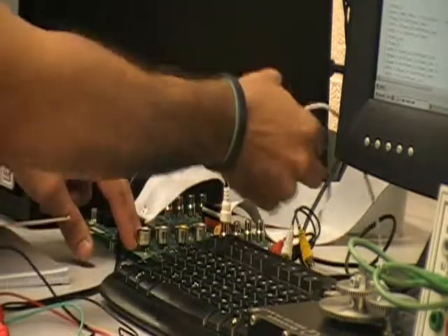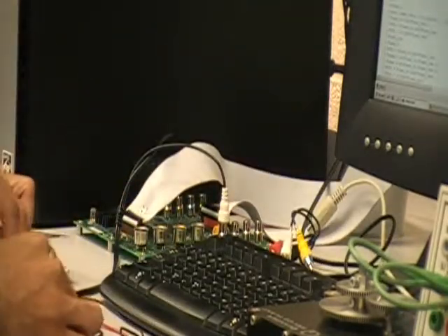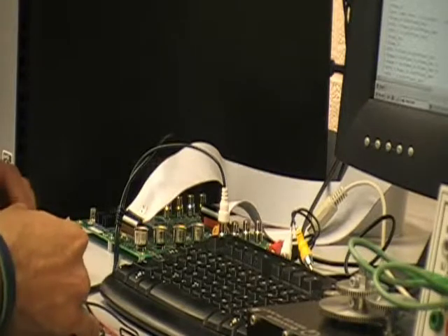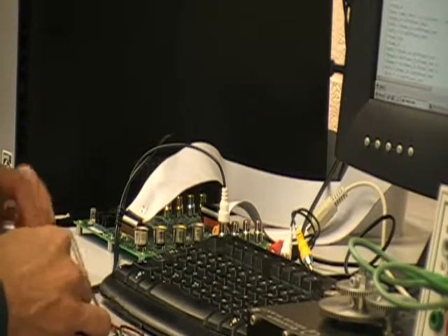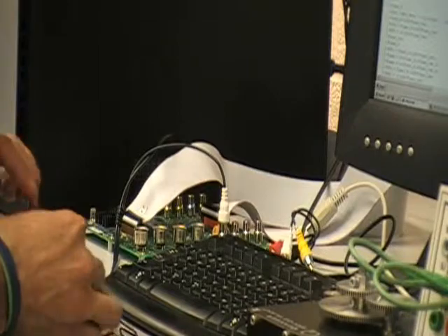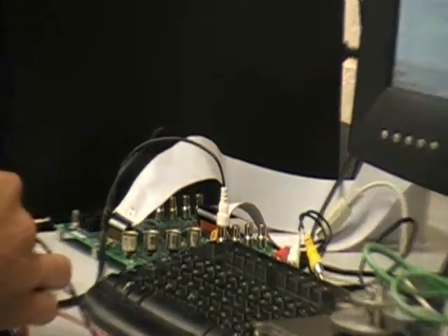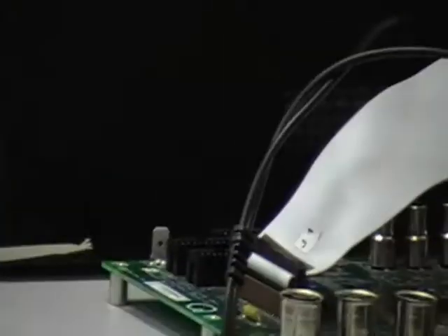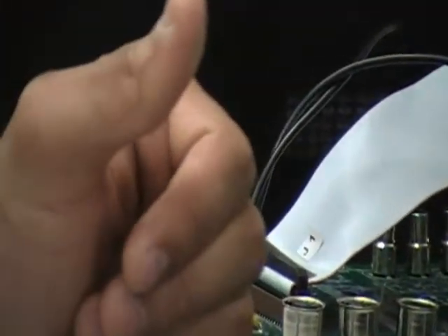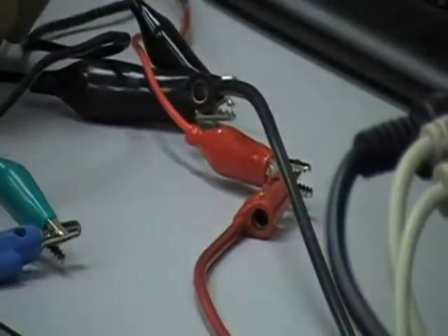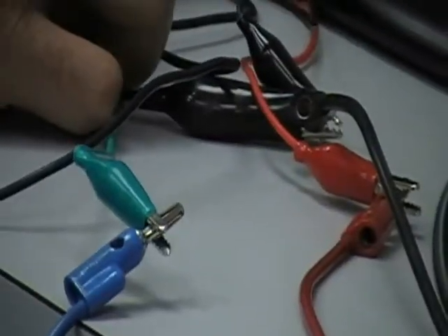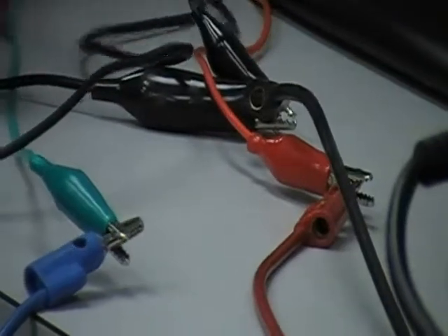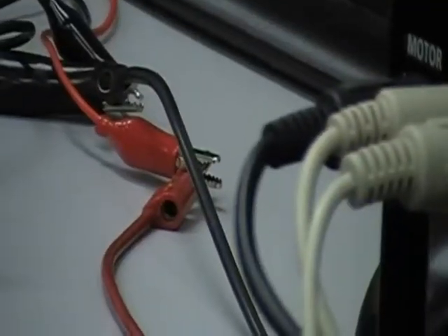It is important to remember the channel number, because if the channel that you plugged the output of the GP6 into is different from the channel in your Simulink, then you will not get any data, and it will just show up as noise. Also, before you start taking data, it is important to check that the connections with the ground and everything are good and nothing is shorted, because if you short them out, you will again get noise and no data, and we don't want that to happen.